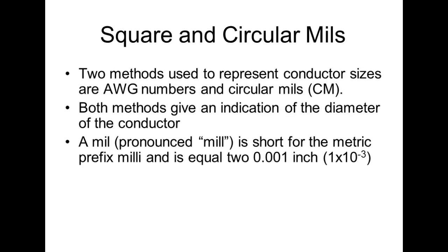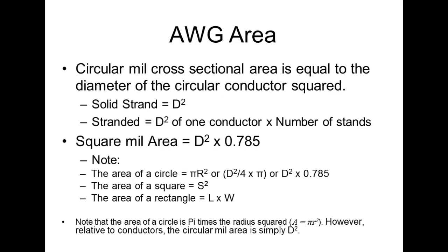There's one thing that I just added to the PowerPoint this morning, just a little different, and that was this right here. And I noticed this. The problem we have with stranded conductors is that as soon as we take the insulation off the conductor, it has a tendency to do what we call bird caging, which means it tries to do what? Spread out. So I don't know if y'all noticed that, but when you do that lab on that micrometer, you need to wrap those stranded wires up and twist them really, really tight. Or if you don't, you're not going to get the right gauge, because as soon as that micrometer hits that side, it's going to push those things and make it try to spread out.